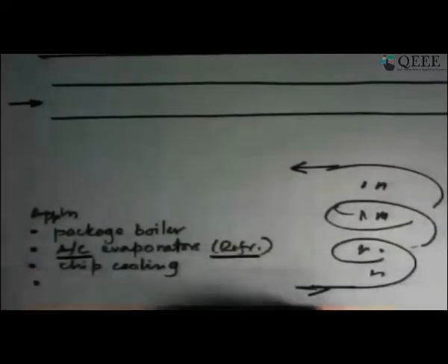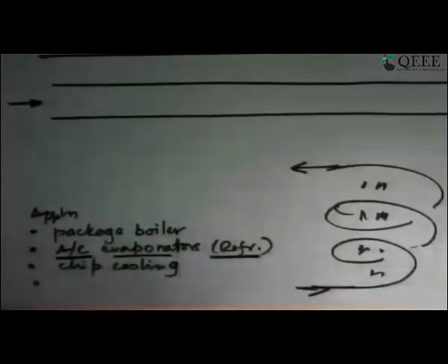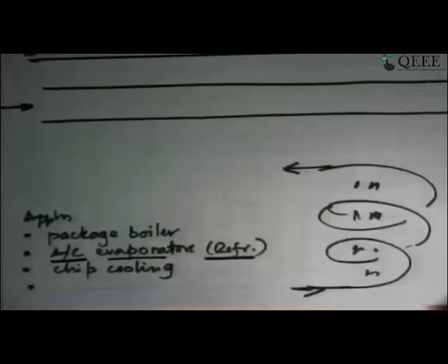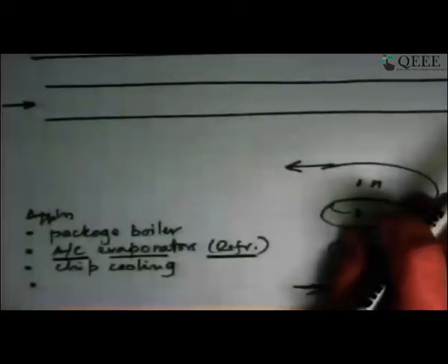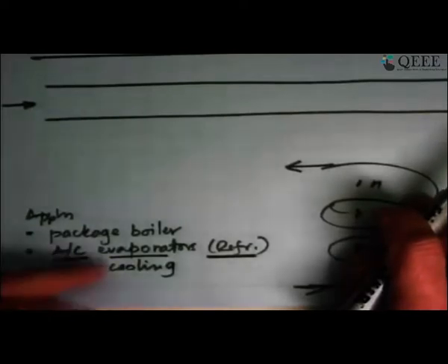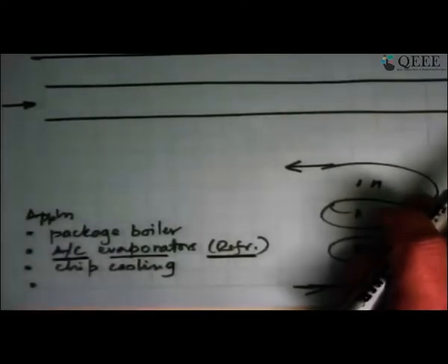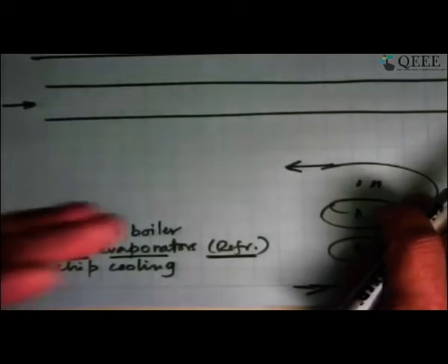We also encounter that very frequently now in all our refrigerators, air conditioning, evaporators. And that's what the evaporator is. Inside this, what is coming in is a subcooled liquid or a saturated liquid at best. And then it gets heated up in the process of cooling the room or cooling the space. A liquid vapor mixture gets heated up. It's a wet mixture which comes out, gets to a dry saturated vapor. Then it gets further heated up a little bit, a slightly superheated vapor, then it leaves. That's how we get the cooling process in refrigerators and air conditioners.